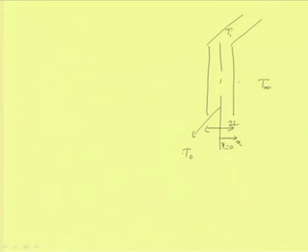So, first we have to find out the value of T0, the center line temperature, and then according to part B, the temperature 0.8 centimeter from one face. Suppose this is one face. So, 0.8 centimeter, total is 4 centimeter. So, 0.8 centimeter from one face, that is 0.008 meter, and from the other face it will be 1.2 centimeter.